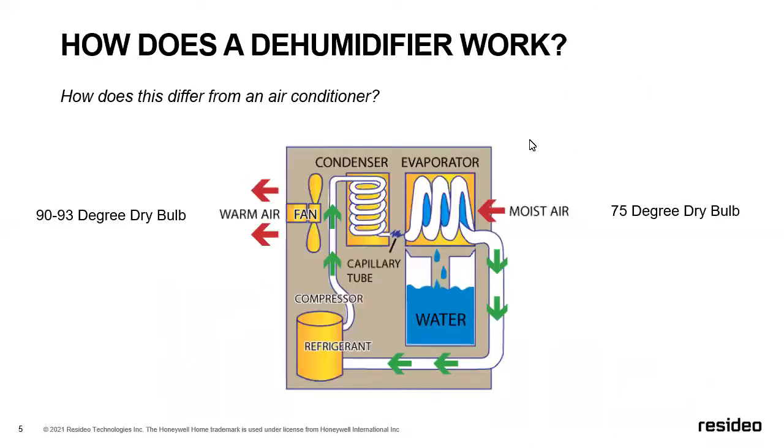All right, so let's talk a little bit about how does the dehumidifier work? I get that question across my desk quite often, and a lot of that's in correlation with the HVAC equipment itself, where we have an air handler and a condensing unit. We have that AC system per se, where our contractors have kind of fallen prey to what some of those manufacturers tell them, that, hey, that AC system is a dehumidifier. And in some cases it is, but it's not necessarily designed wholeheartedly to be a latent heat remover, right?